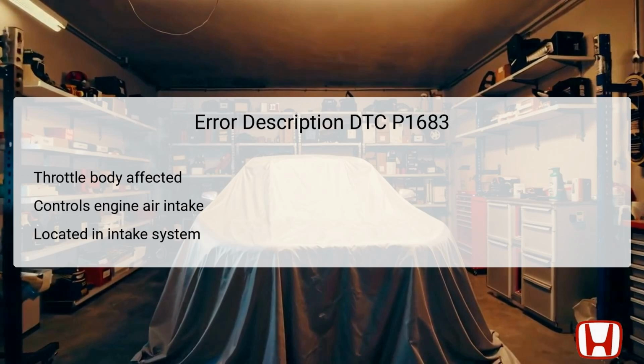If the throttle valve fails to return to its default position, it indicates a malfunction in the throttle valve spring. This failure can lead to a range of issues, including poor engine performance and potentially unsafe driving conditions. The Engine Control Module, ECM, monitors this functionality, and any deviation from expected performance triggers the DTC P1683, which alerts technicians to the underlying issue.